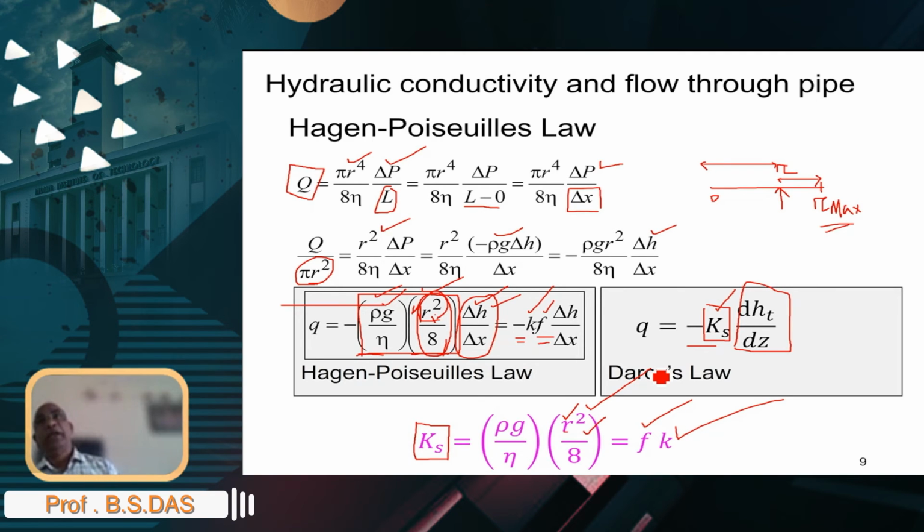Now the way we describe this pore size in the context of water flow, we characterize it with the water containing pore, right? So if not all the pore spaces contain water, that's what we are talking about. So the amount of water present in soil is going to be less than the saturated water content, right? And so therefore the conductivity would drastically reduce with the radius of the water containing pore, and drastically also reduce with the reduction in the soil wetness.